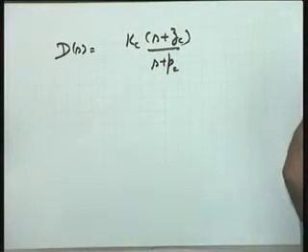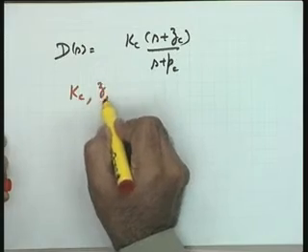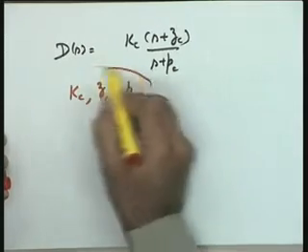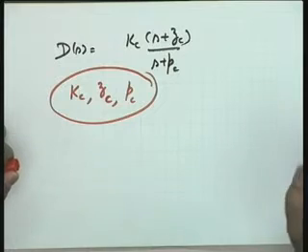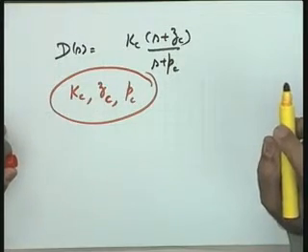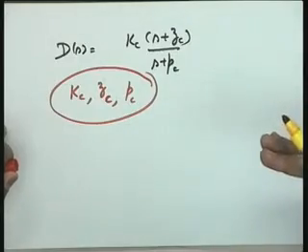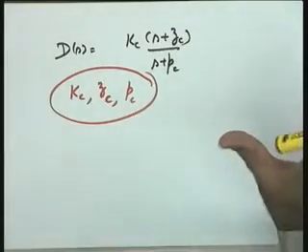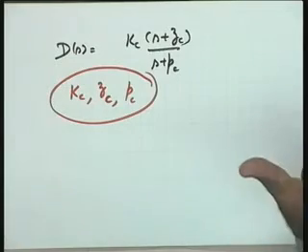Okay, so see that this K has been replaced by this particular compensator Kc (S plus Zc) over (S plus Pc). So there are three parameters, Kc, Zc and Pc, which you can manipulate. You see that the compensator design becomes more logical, the steps become more logical, if I reformulate my problem like this. I am sure you will appreciate my point and raise a question if it is not clear.